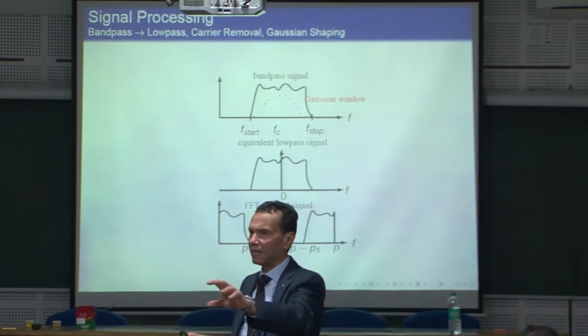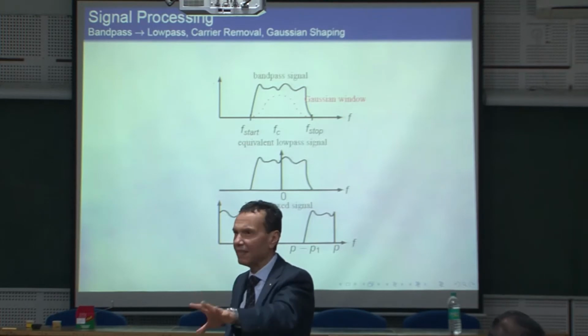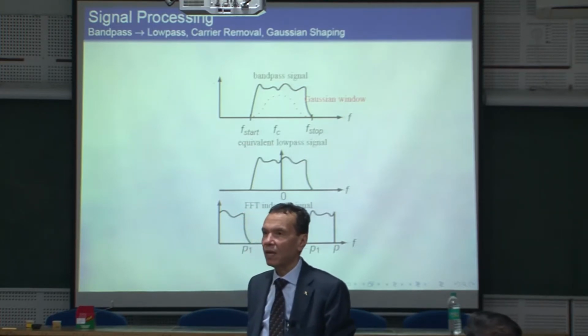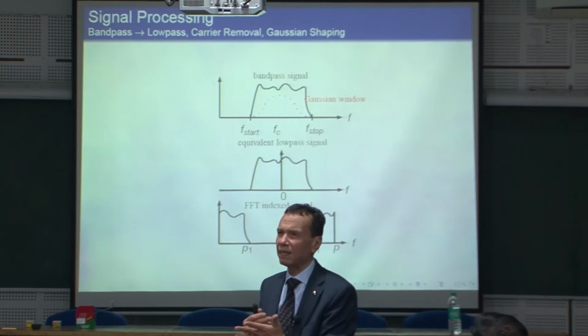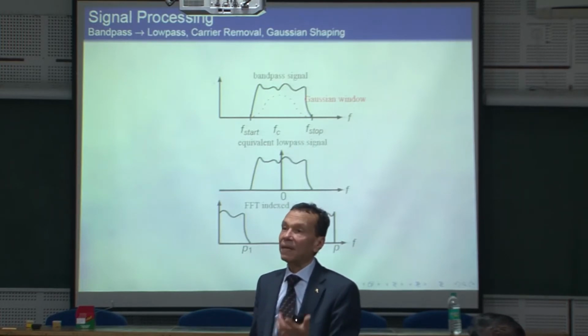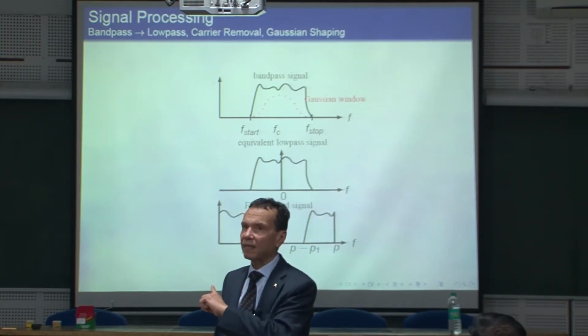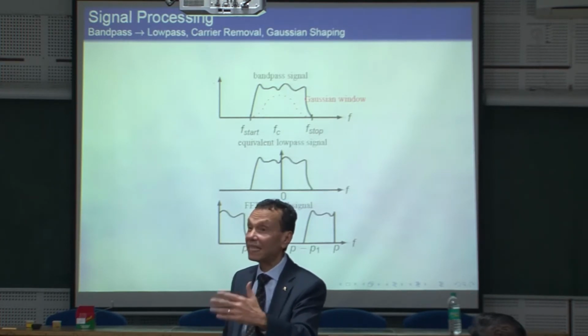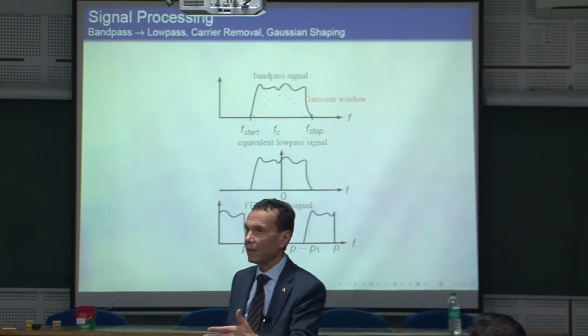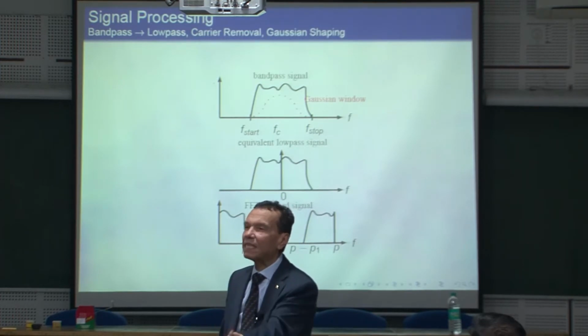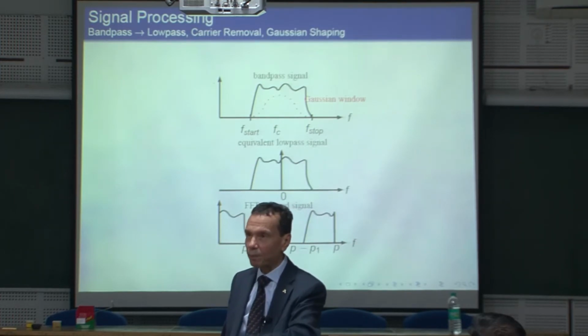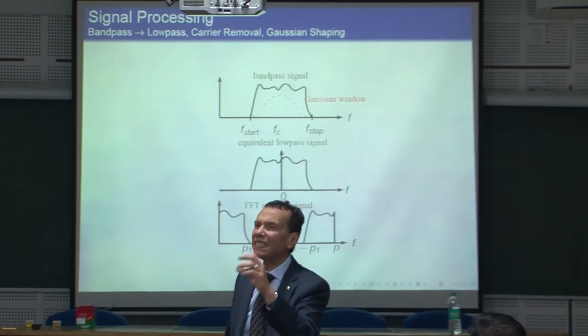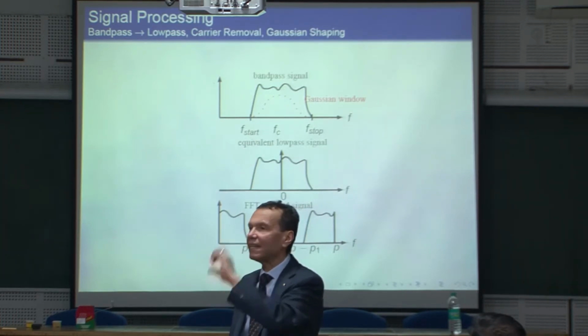I can say, okay, I can identify it as this, and let us get rid of it. Of course, if they are nearby, it will not be easy. But if they are not nearby, the other technique is, okay, let us make a model for this strong reflection. I know it is not exact, but I will subtract it from my measurements so that if it still exists, it is weaker than in the past.